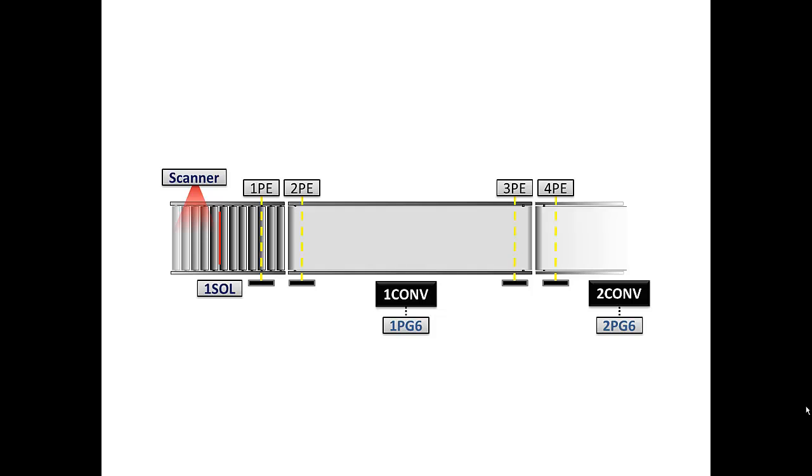We're going to add a couple more devices. Our conveyor motors each have an encoder or a pulse generator attached to the output shaft or the drive shaft of the conveyor. And basically this PG, pulse generator, will put out a symmetrical pulse, or it could be asymmetrical, but it'll put out a pulse for every so many increments in inch that the conveyor belt travels. Now it's actually putting out a pulse based on the rotation of the shaft, but the rotation of the shaft can be directly correlated to the circumference of the drive pulley.